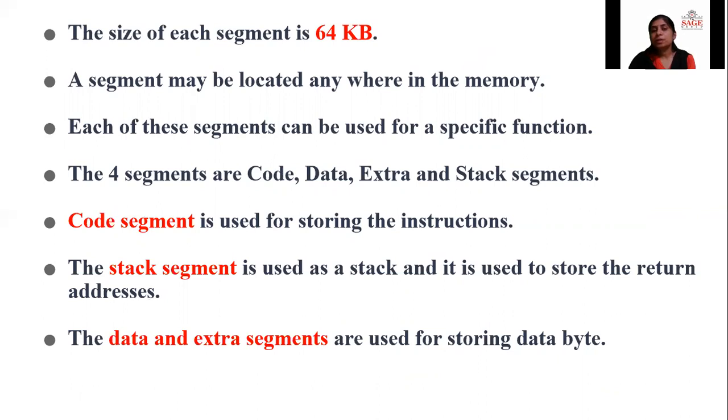Each of these segments can be used for a specific function. The 4 segments are code, data, extra, and stack segments. The code segment is used for storing the instructions. The stack segment is used as the stack, and it is used to store the return addresses. The data and extra segments are used for storing data bytes.